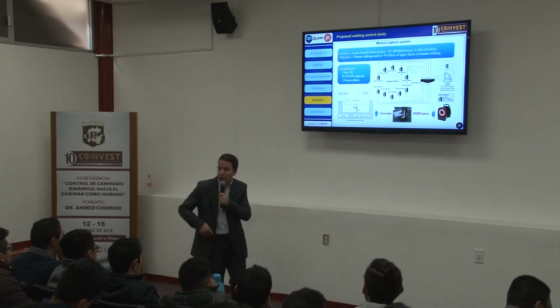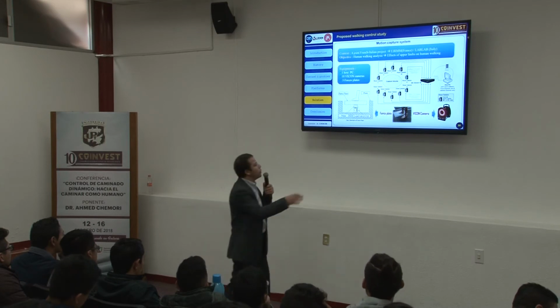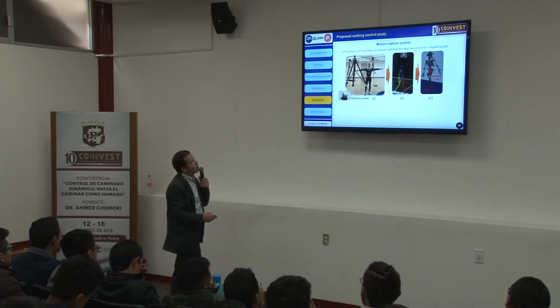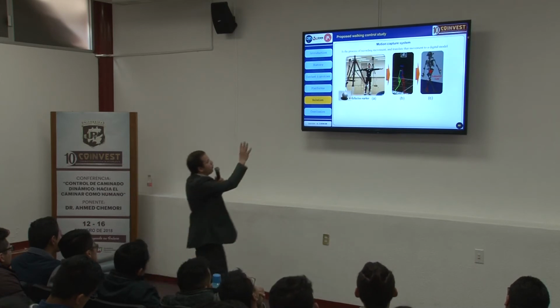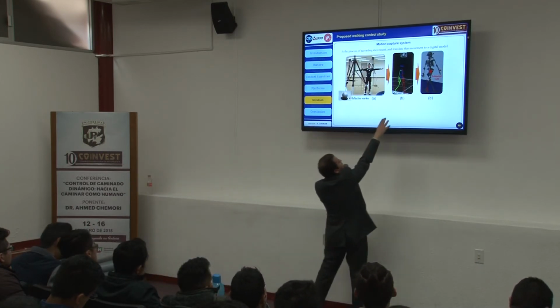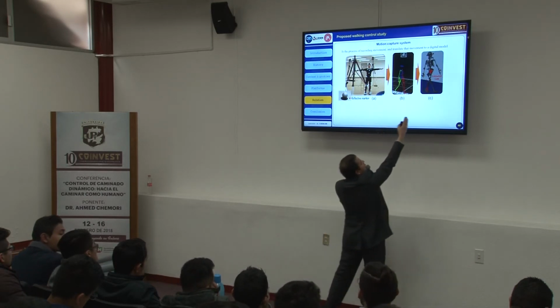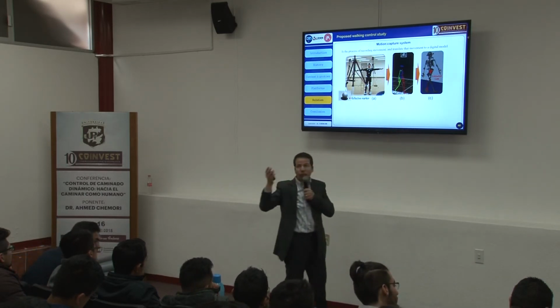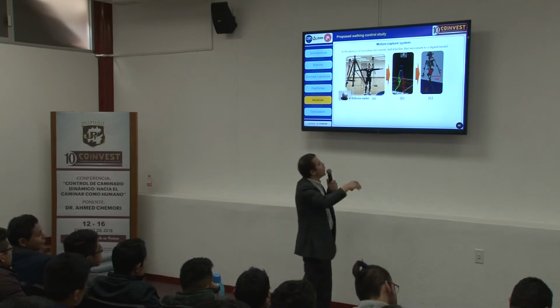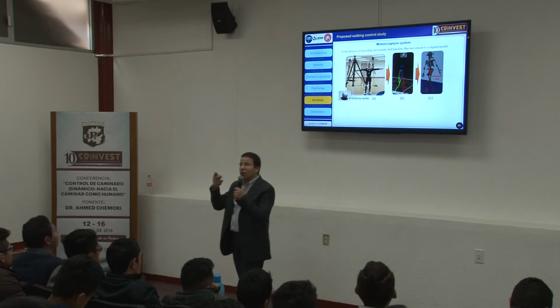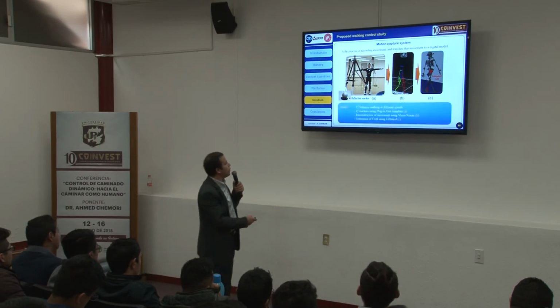When we walk on this, we can measure the contact forces with the ground, and we use the cameras to localize the markers in space. Then, from the markers, we can have the walking of the human represented by this model, and we can have more detailed information if we use another software like Life Mode, for instance, where we can have the position of the center of mass in real time, how it evolves.